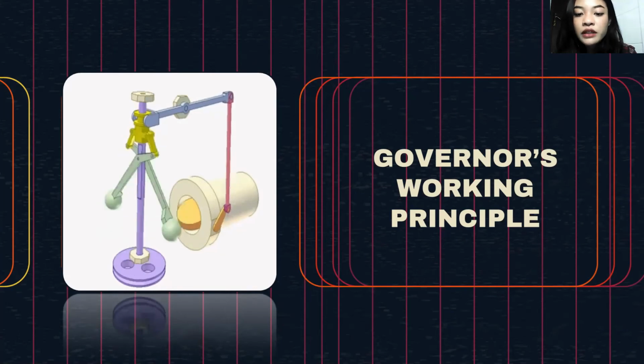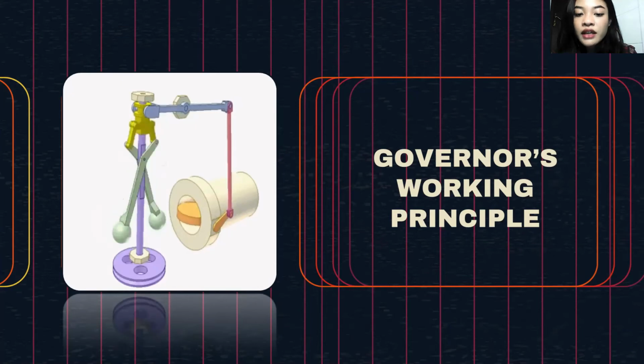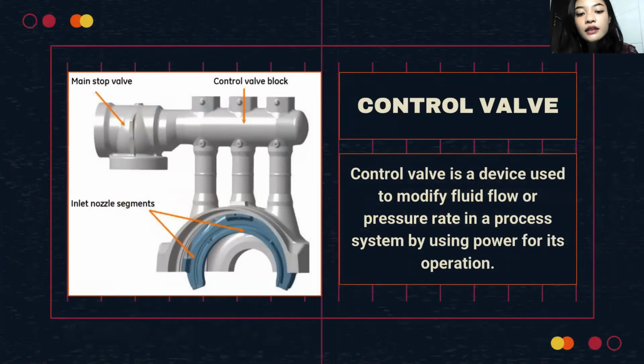The collar movement is used to operate or set the fuel lever on a diesel engine or the flow valve in gas or steam turbines. The spin rotation is kept at the desired set point value, 3000 rpm, so that the electricity generated by the generator stays at a certain frequency, which is about 50 Hz.